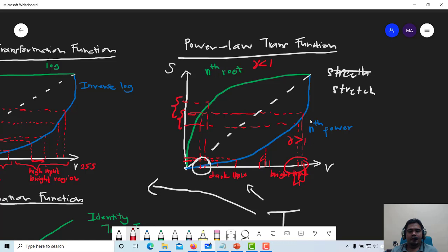You can see over here, if you apply this one, yes, you are improving the bright side because everything in the bright you will stretch, but everything in the dark input you are compressing, narrowing down from the wide range into a narrow range, meaning that the dark region will be compressed and more information lost, but you are stretching the bright information. That's why you get more information on the bright side, but you lose information on the dark side.